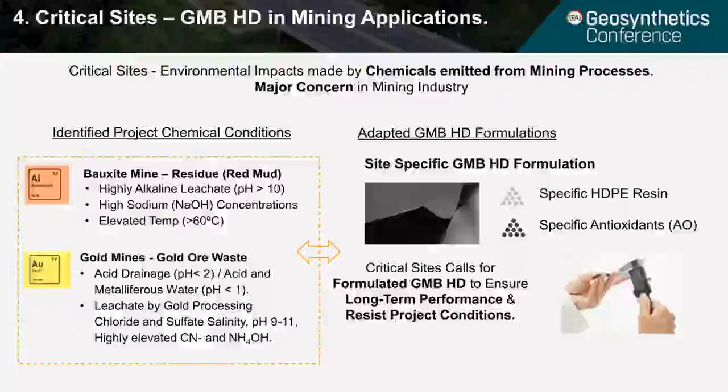As such, these critical sites call for geomembrane HD formulations with specific HDPE resins and specific antioxidants to ensure long-term performance to be able to resist project conditions.